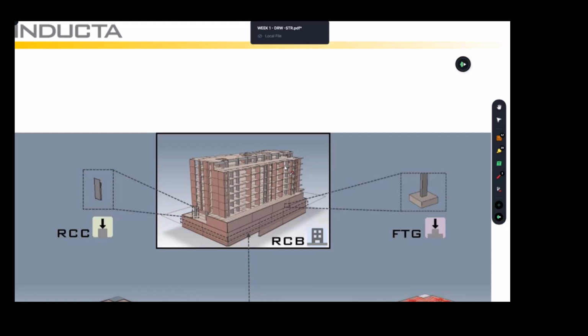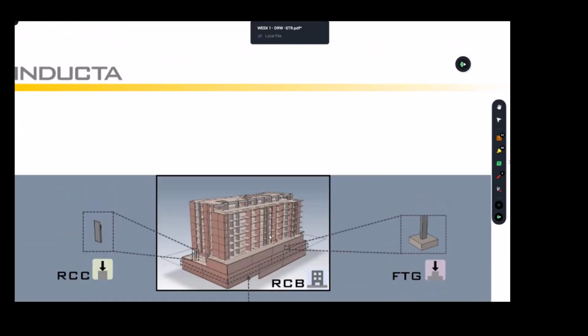So it's possible for engineers to simulate what you're learning here with Space Gass, but you have to simulate the sticks as accurately as possible to reflect the core structure, which we talked about and you're going to be checking. If you manage to correctly simulate that core as a stick, with the correct Ixx and Iyy that I was talking to you about, you can be almost there with some safety factor, which is fine. Okay, so that's RCB.